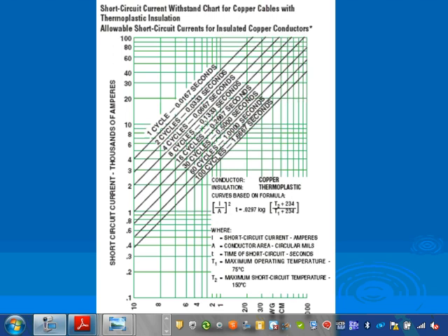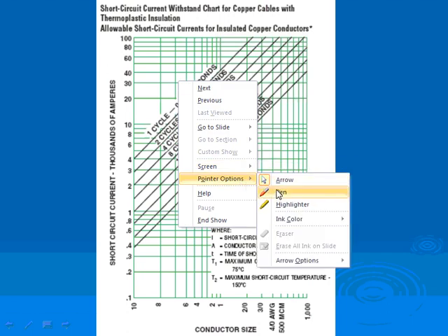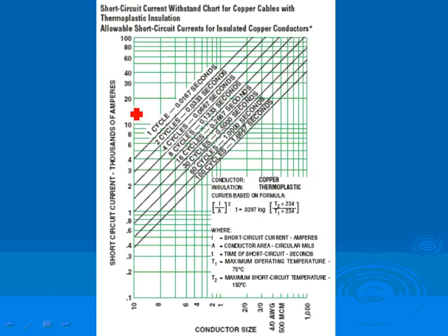So let me show you an example. So suppose that you size a conductor, and based on the size, this is right here, short circuit in thousands of amps. So suppose that my short circuit is 20,000. Can you guys see that? So 20,000. Now, if I trip within one cycle, am I here? Is that the same line? Yep, it's the same line.